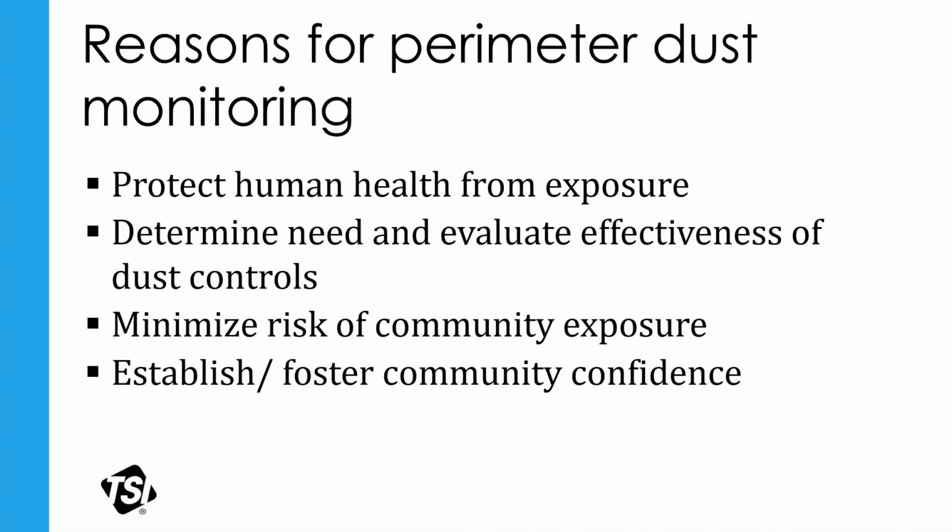So, big picture, why are we dust monitoring? Obviously, we're concerned with human health, for employees, subcontractors, and even the community at large. Really, we're doing a lot of these things because we may be digging up something from the earth that we don't want people breathing in. We use perimeter monitoring to determine, do we even need to have any kind of dust suppression? Do we need to be sending alerts to the community? And now we can show whether the things we're doing work or not.